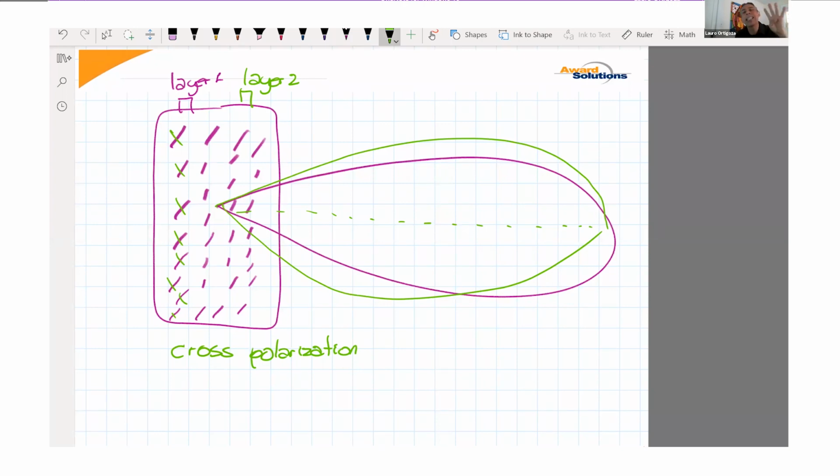All right, so let's go back to multi-user MIMO really quick. In multi-user MIMO, this is going to be my sector, just like in LTE. However, we are going to cover this sector with beams. In this case, the gNB is capable of transmitting 4 layers with 4 subarrays. But my receivers are user number 1 and user number 2. User number 1 is Alice, and this is Alice and Bob. Alice only has a device that can receive with 2 antennas, right?